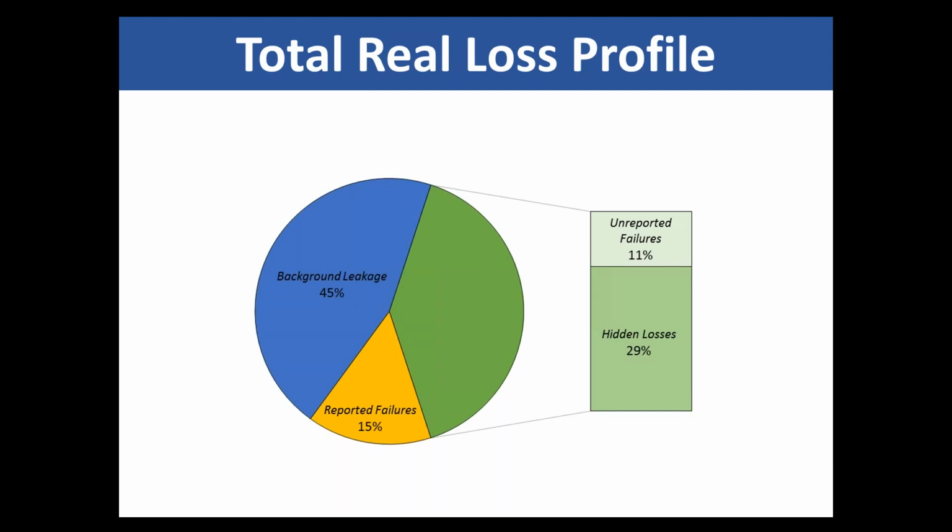So then we went back to reviewing what they're doing, and it was a function of how the survey was done, because they were just going from valves to hydrants and not really listening to the service connection, so that they were missing a lot of the leaks. And that then informed the decision. Well, we're going to tender again and figure out that we get a survey that is very detailed, because if we're surveying 30% of our system, we want to recover leakage in a similar magnitude to that. Does that make sense?